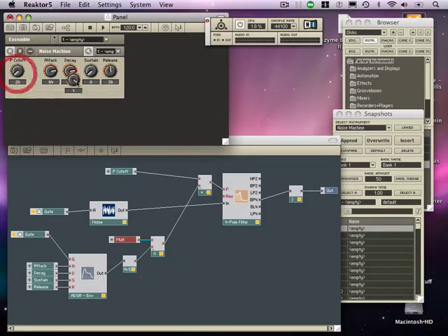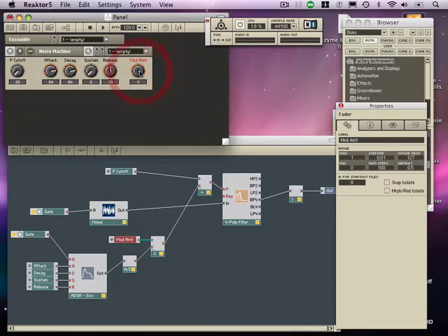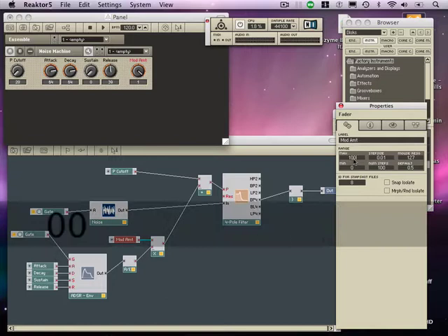Unlock the panel, let's move it over. I'm going to rename this mod amount, and we need to actually tamper with the parameters here to make it work how we want. I'm going to push F4, going to select the mod amount, and I'm going to set a range max of 100 and then a minimum of -100, and this is going to give us the strength control that I'm going to demonstrate in a minute. So that's the circuit done.